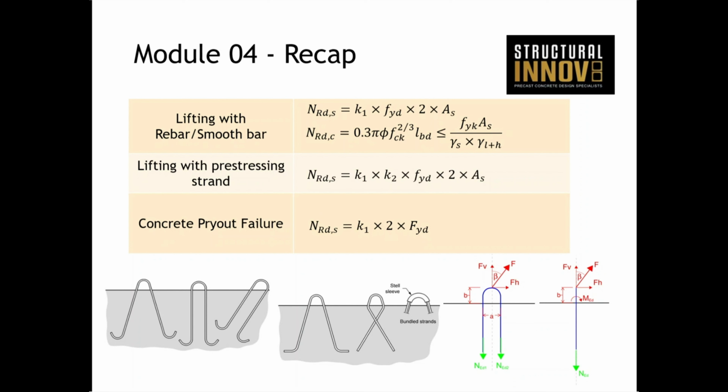So you're checking in terms of the steel checks, you're primarily in tension, and you're just checking the cross-sectional area of the lifting loop. And in terms of the concrete checks, you're generally checking the anchorage. I just noticed a typo on my slide here. I'll have this corrected before we issue these out. So this is not concrete pry-out failure. This should actually say wire loops.